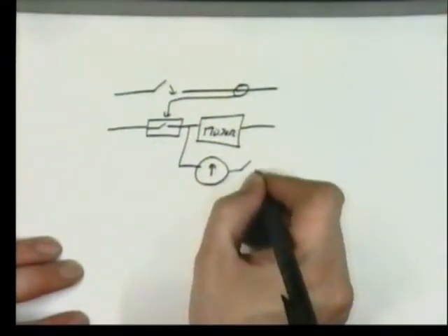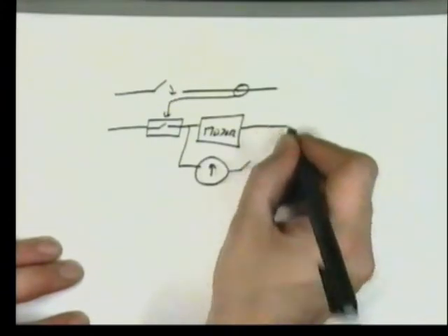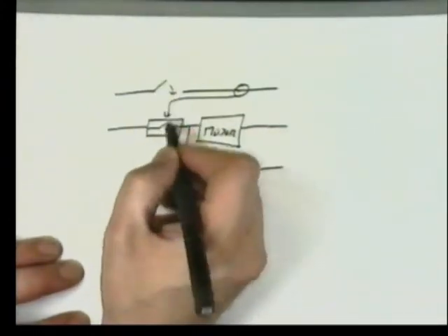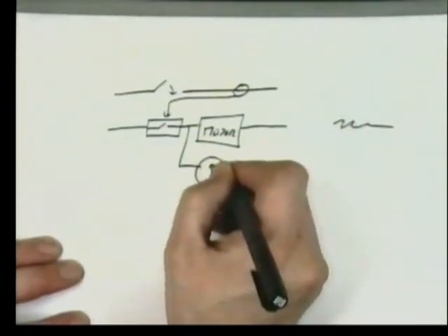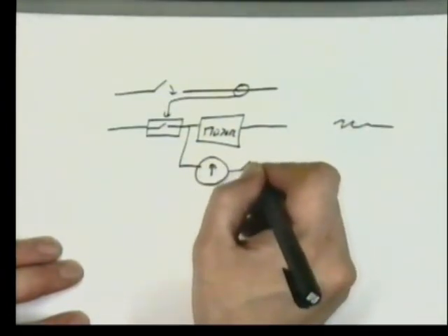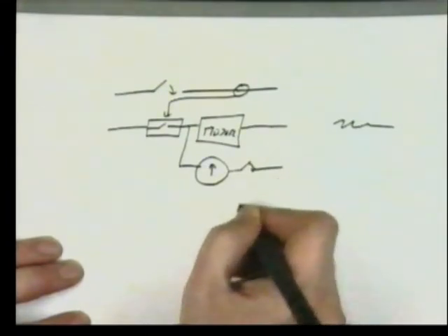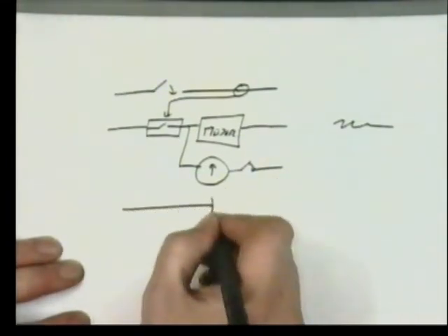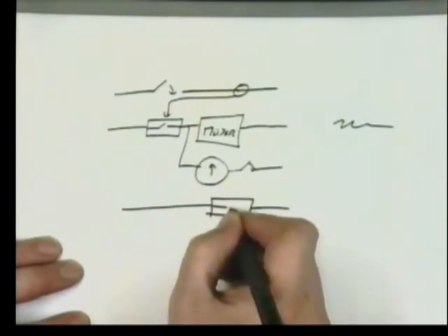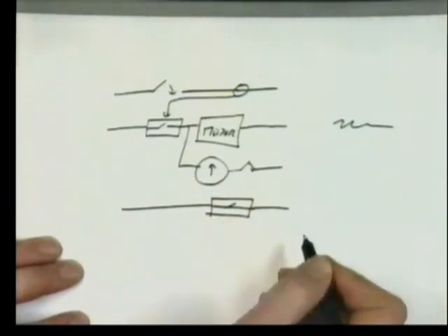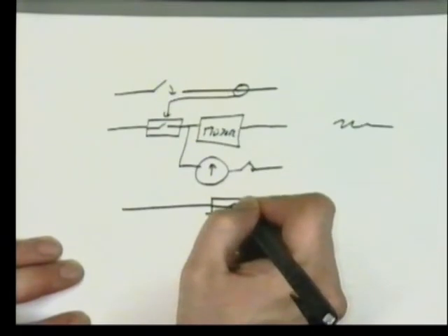And let's have here another switch. So what's going to happen is that this switch turned on the motor, so now something's happening, but the timer's timing. When that timer finally times out, that switch will close. We could have made that be a relay that when that closed, opened. So that closure makes that open.